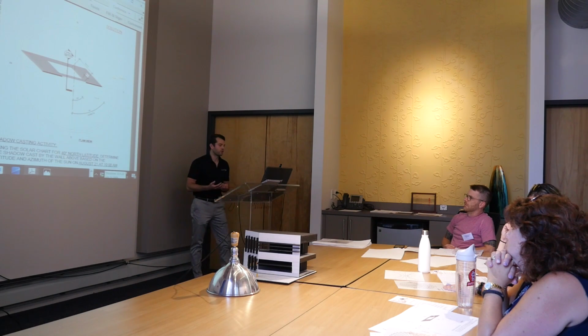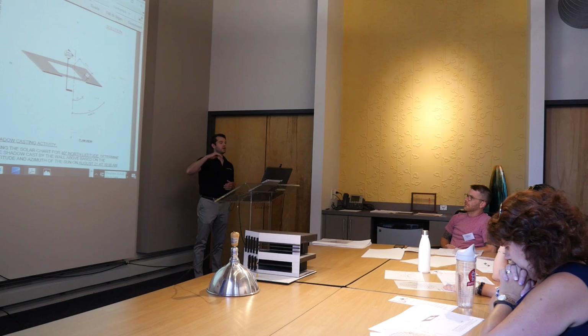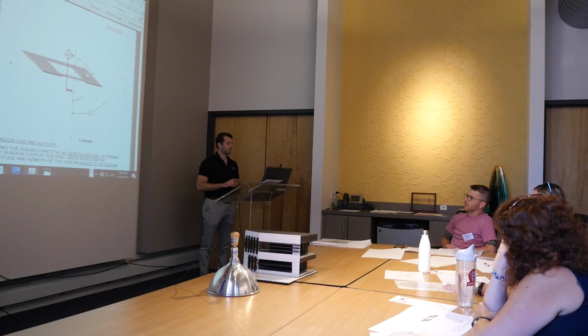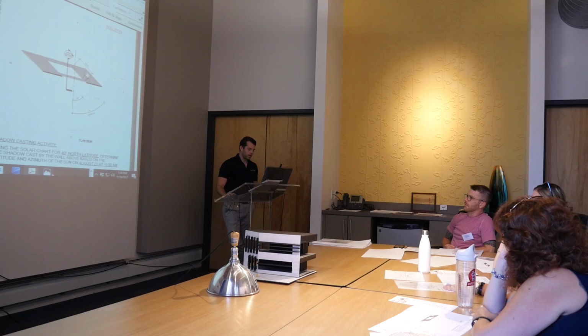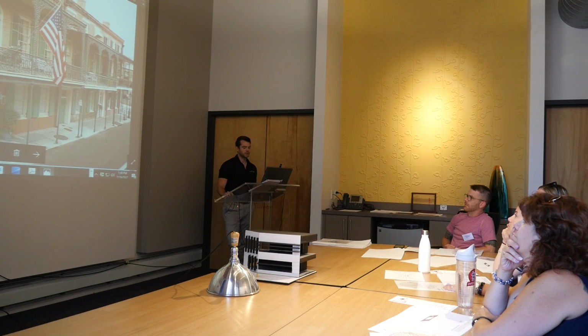And it's really important to find that angle because, as you already know, I'm sure, in the summer, the sun's much higher, it's much hotter. In the winter, it's much lower. You probably want some of that light in your building because it warms the space. So how we design our window openings has a big effect. And you'll find that on historic buildings even, things that we take for granted were actually designed a lot because of solar and the climate.